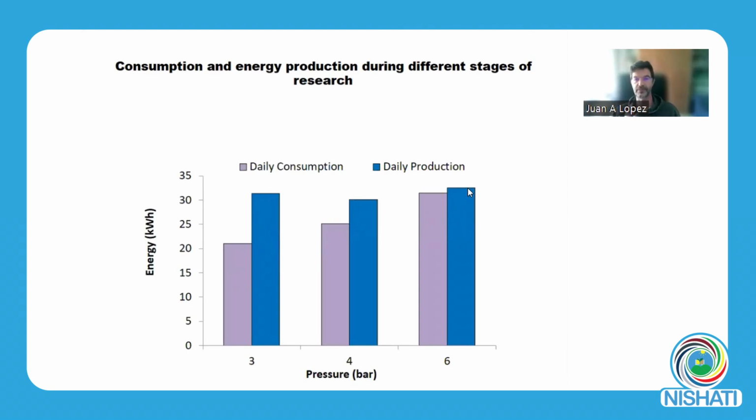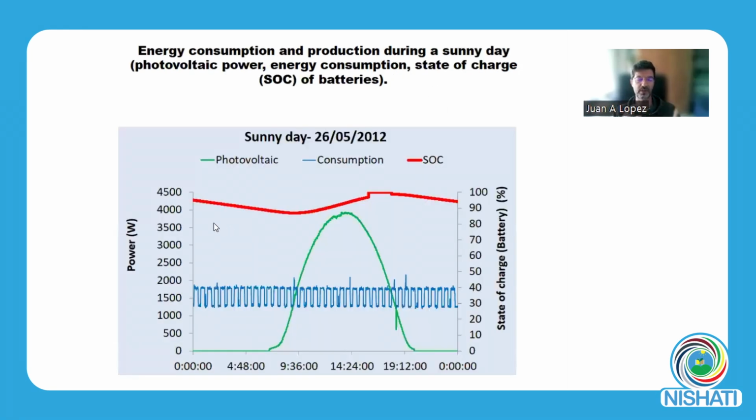We use nanofiltration because the amount of energy that you need for working is lower than reverse osmosis, and the water quality is almost the same. So I decided to use nanofiltration and not reverse osmosis.